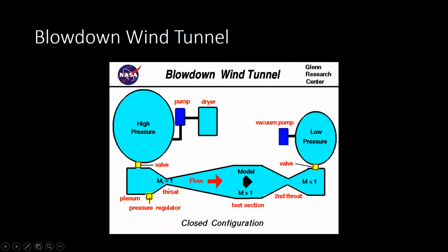The reason this doesn't really work is because subsonic flow is incompressible, but as you move to supersonic or maybe even transonic flows, you reach a compressible state. This way your turbine is less effective because it's only really designed to move a lot of mass and add a little bit of velocity to it.